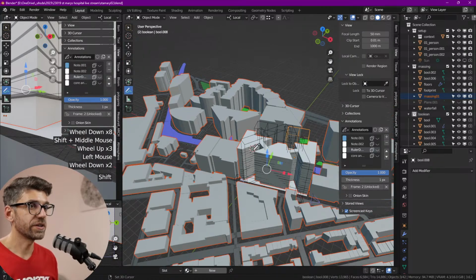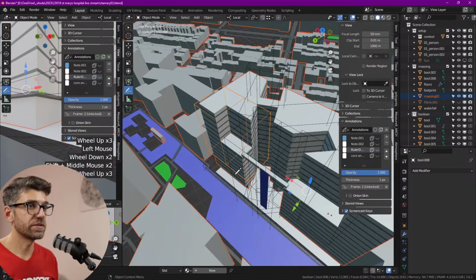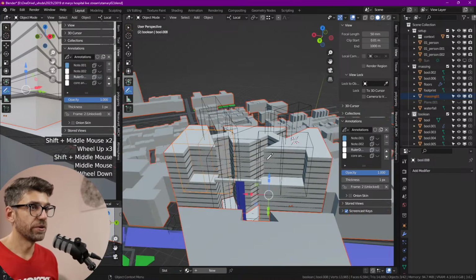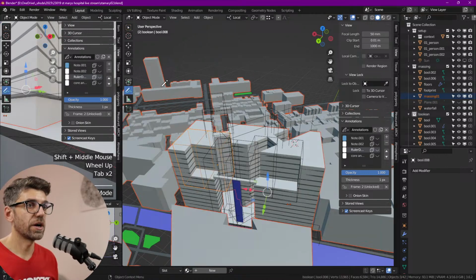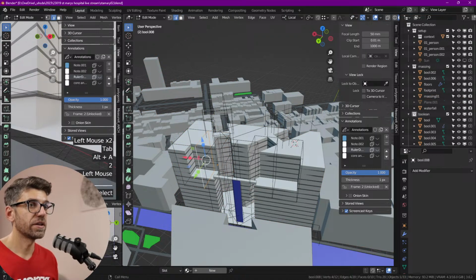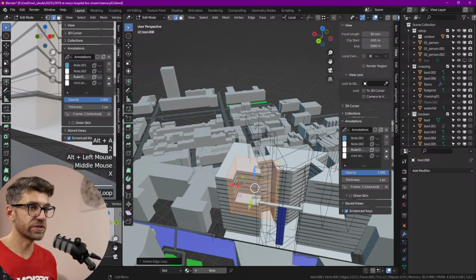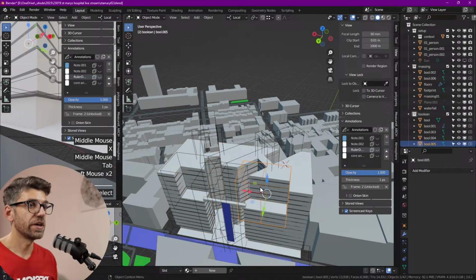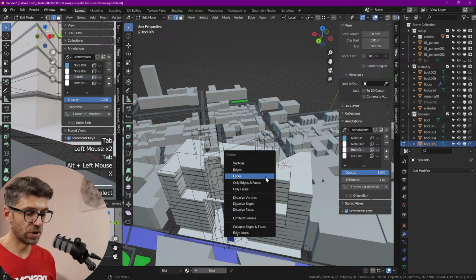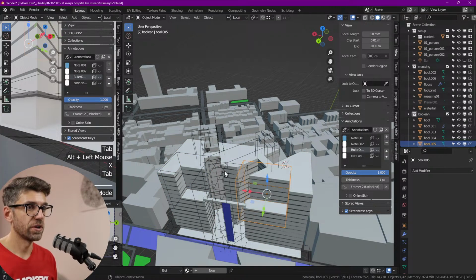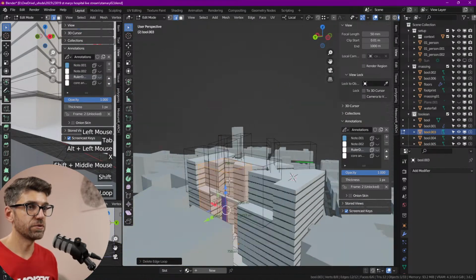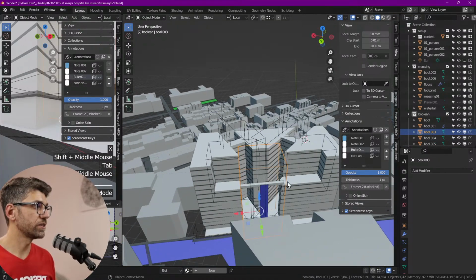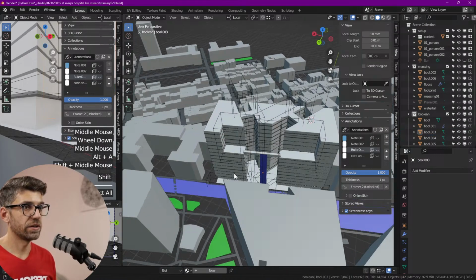Very well. Let's carry on now with our setbacks of the massing. So 10 floors, this is pretty good. It does get maybe a little bit hard to read at some point. You know how we created that pointless loop cut in here? Sometimes those loop cuts do help, by the way. Like in booleans, if there are errors, having a little bit of subdivision in the geometry helps resolve a lot of those potential errors. But right now our shape is fairly straightforward, fairly simple, and it seems to work pretty well. So we've got this going on here.